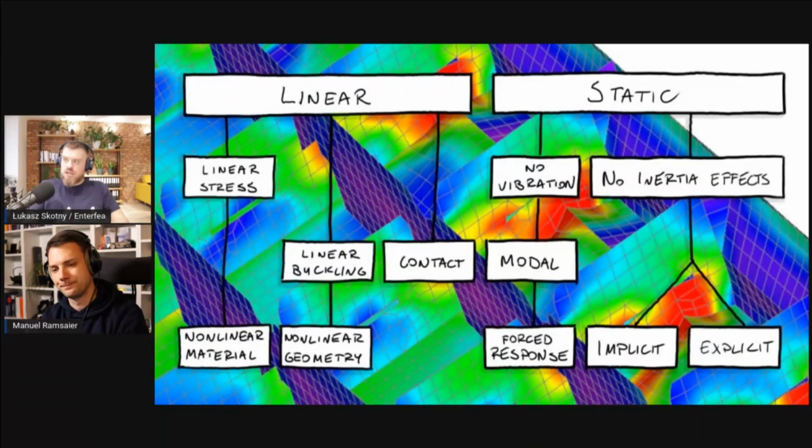If you solve thousands of the same models, from experience you can derive something like, if I'm solving the same thing over and over and I get a buckling multiplier of this much, I will be okay. That's reasonable. But there are no general rules. You would have to be really careful about who tells you what the limit is and how they derived it, because it would have to be specifically tailored to whatever you're doing.